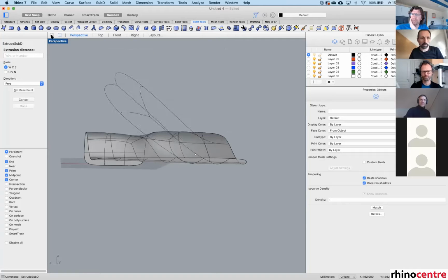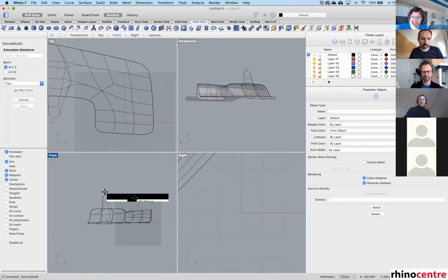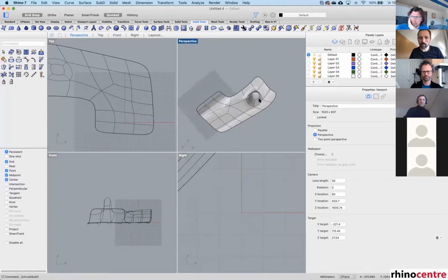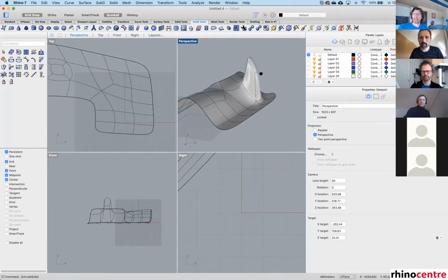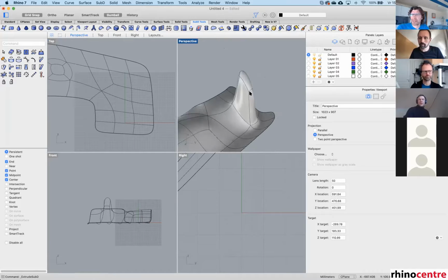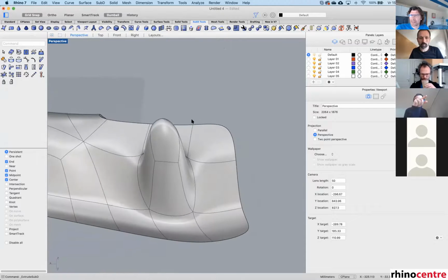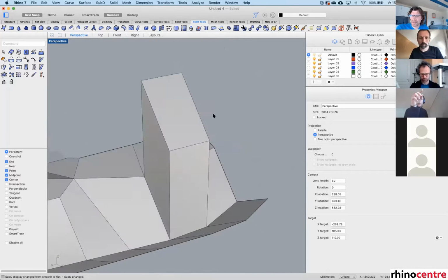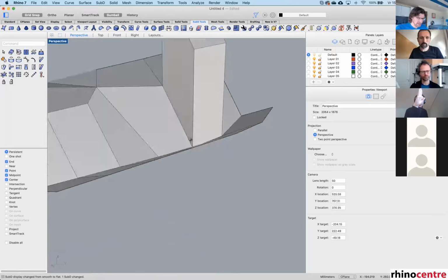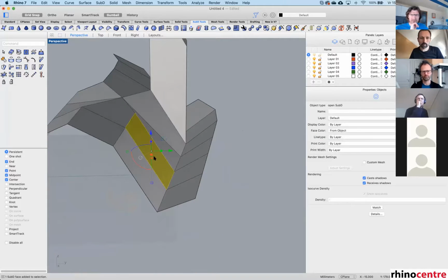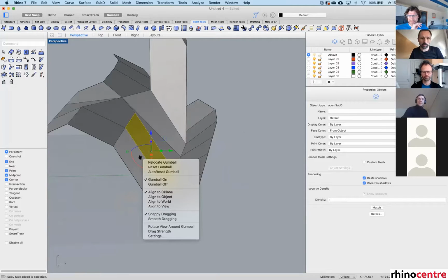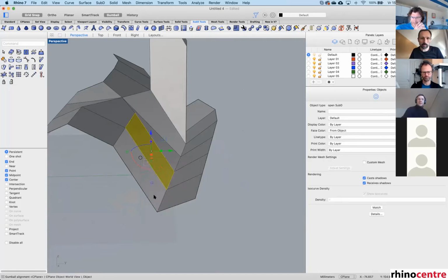This is a little bit confusing at the moment, so now I'm drawing up. And then you get the same kind of extrusion. And it's very important, if I'm correct, you can extrude in different directions. There's an option on the gumball or somewhere where you can choose to extrude along the face normal also. Yeah, so you can align your gumball to be auto-aligned with the object.